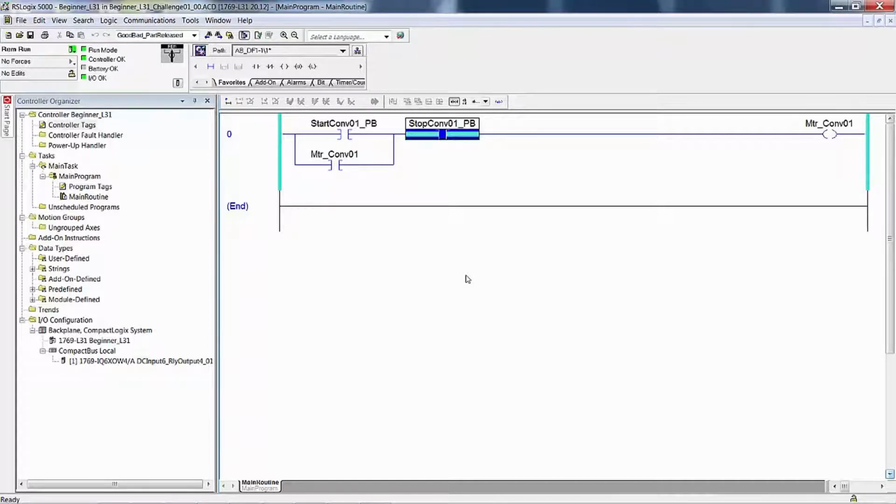That simulated pressing, turning off the normally closed contacts and releasing, turning it back on. This leaves the rung of logic in the state of rest: normally open buttons off and normally closed buttons on. Okay, that concludes the testing of your logic online in the run mode without the benefit of real I/O.